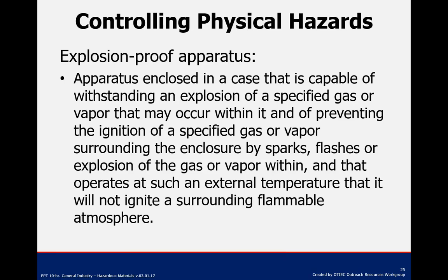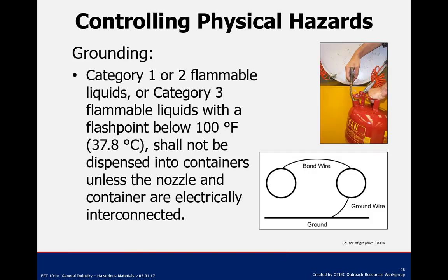Explosion-proof apparatus is enclosed in a case that is capable of withstanding an explosion of specified gas or vapor that may occur within it and of preventing the ignition of a specified gas or vapor surrounding the enclosure by sparks, flashes, or explosion of the gas or vapor within, and that operates at such an external temperature that it will not ignite a surrounding flammable atmosphere.